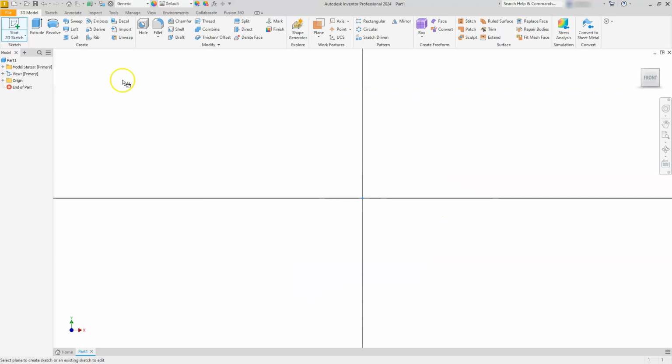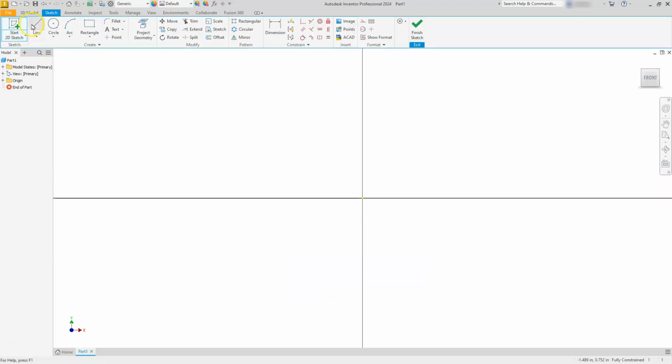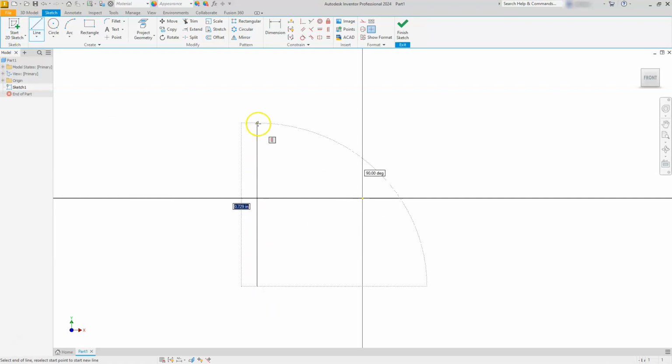Alright, so once I have this selected, I'm going to start with the line command. And I'm going to create a vertical line. I'm going to click here, and then I'm going to go up. You'll also notice that there's an icon near my cursor showing that that is the direction of vertical. So while I'm pointing this up, I'm going to type in that long number, the tallest number of my center line. I'm just going to type in 25, and hit enter.